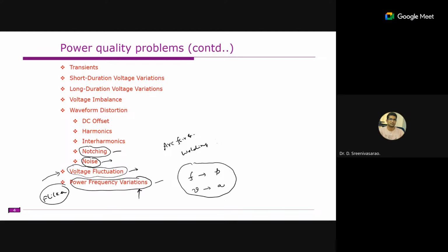In the case where the short circuit ratio is very high this holds, but where the short circuit ratio is very low, the rules will change. Now we have microgrids and so on, so we can expect this. We will inject a lot of active power into the microgrid, and we will draw more active power from the microgrid. Therefore, frequency variations are very common nowadays.